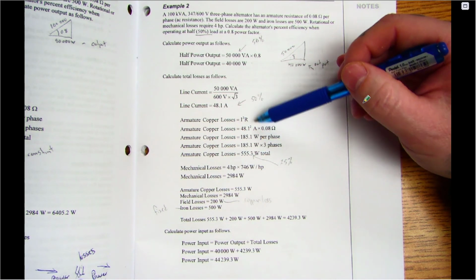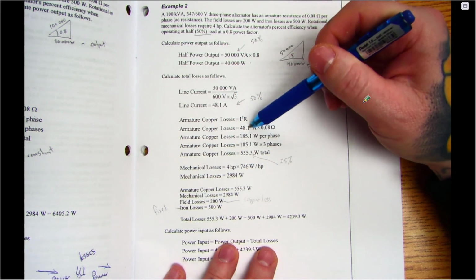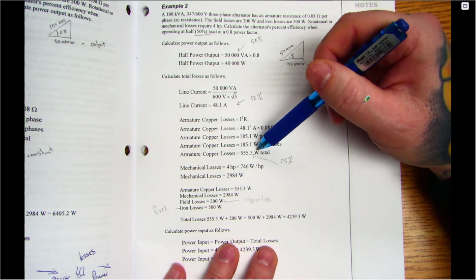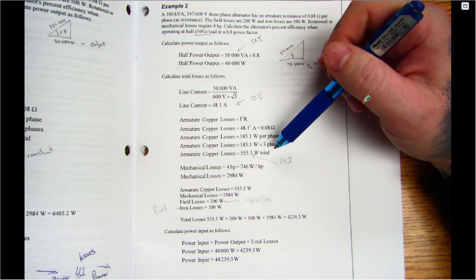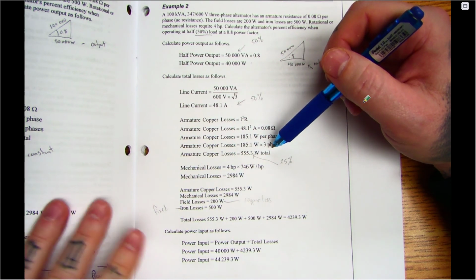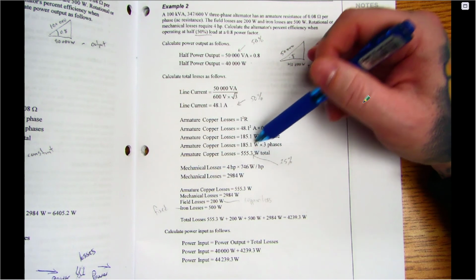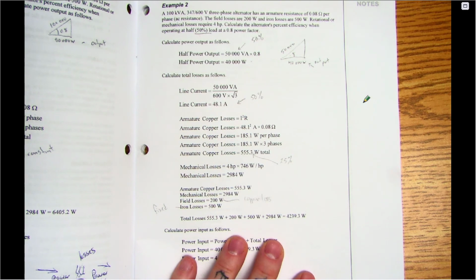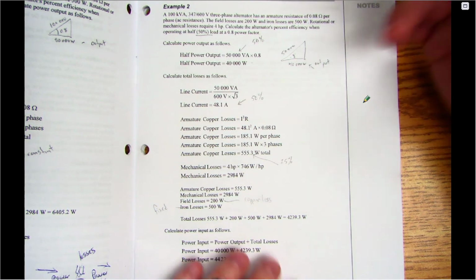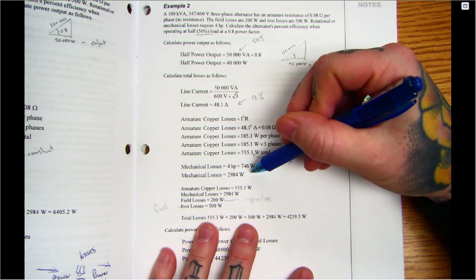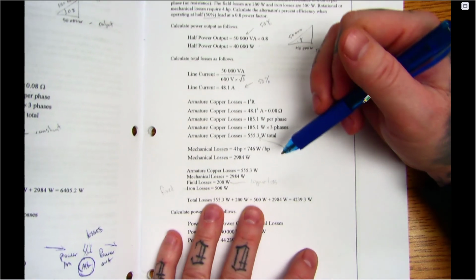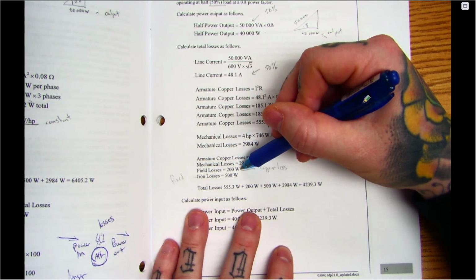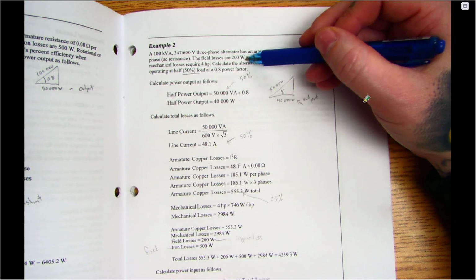Then when we go finish, get all our losses, we're still using our I squared R losses, but because of that squared portion, these losses are actually a quarter of what they were instead of half. Okay, so we had 2,221.2, but because of that squared portion of our current, we see a 75% reduction. I guess we only see 25% of what we had. The wattage will be the same. Mechanical losses are the same. The other thing that changed was our field loss because they have copper in them too. So they addressed it here by just changing it to 200.